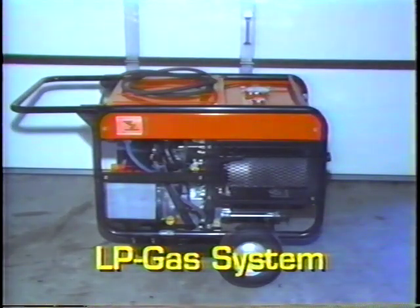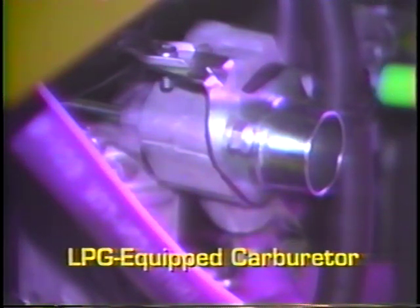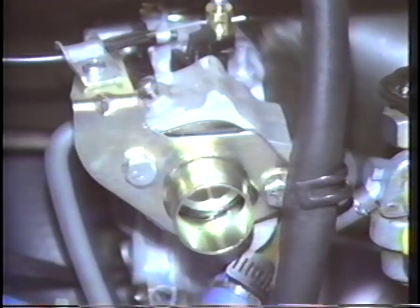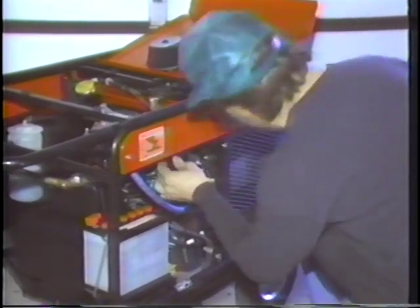An LP gas fuel system usually meters liquefied petroleum gas into a conventional carburetor. Since many will operate on both gasoline or LP gas, they're termed a dual fuel system. A gas pressure control valve and other parts must be installed on the engine so that it can burn LP gas. The LP gas is desirable because it produces less exhaust emissions and less internal engine deposits.